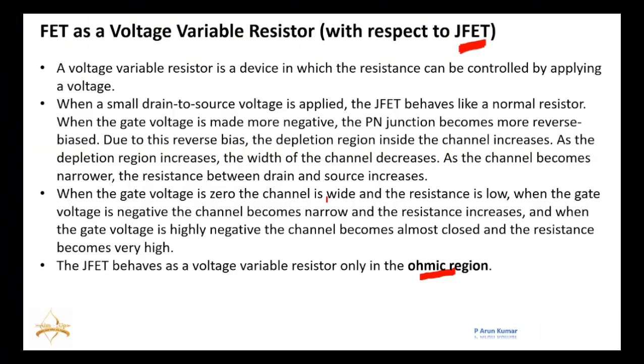Now, the N-channel enhancement MOSFET. Now we'll see. To discuss this N-channel enhancement MOSFET, first of all, let me try to define its construction. Here also, I'm taking one pure semiconductor. In this pure semiconductor, I'm doping with trivalent impurities. Then it will turn into a P-type. On the two sides of this P-type, it will be doped with pentavalent impurities. It will turn into an N-type.